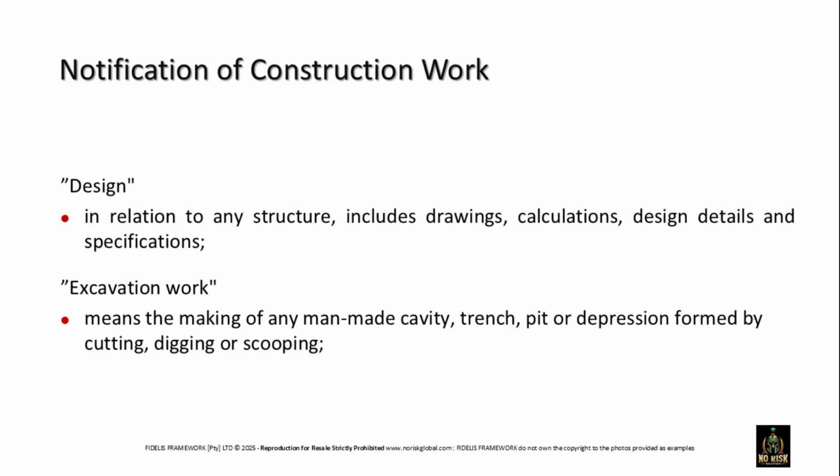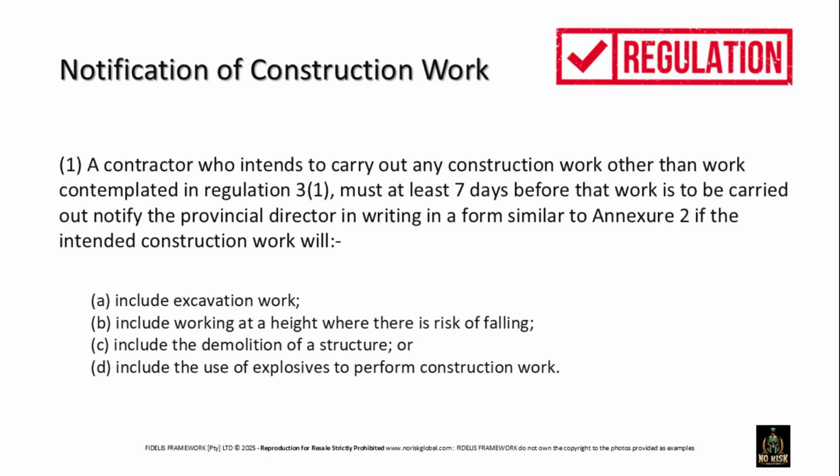Notification of construction work includes design and excavation work. Contractors must notify the provincial director in writing at least 7 days before starting work involving risks like falling or using explosives. For construction work involving single-story dwellings intended for client residence, contractors must notify the provincial director at least 7 days before work begins, using a form similar to Annexure 2.